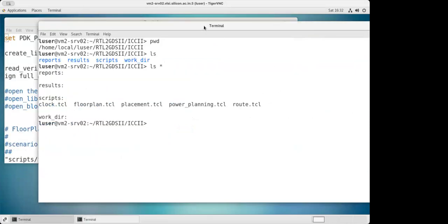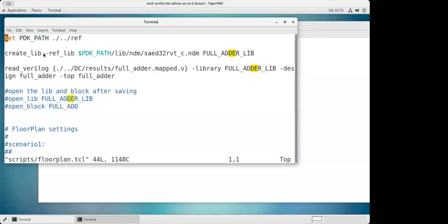Okay, so when you are inside the ICC2, do icc2_shell and enter. This is something all of you have to do. Just do icc2_shell, let the ICC2 shell come. The way the DC shell was coming, similarly the ICC2 shell will also come. In the meantime, let me explain what we are going to do as part of the first script file, which is our floorplan file.